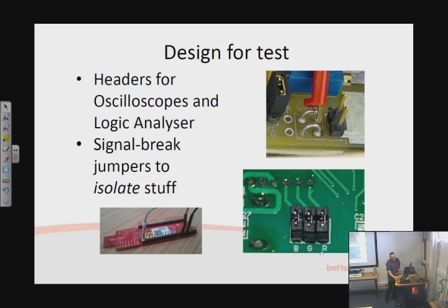Now, if you develop a PCB and you've got separate parts of that PCB, why not design in some little jumper links that you can completely shut down one part of the PCB and develop just the other, if there's a suspicion that the two might interact with each other. We can also depower things using links and things like that.